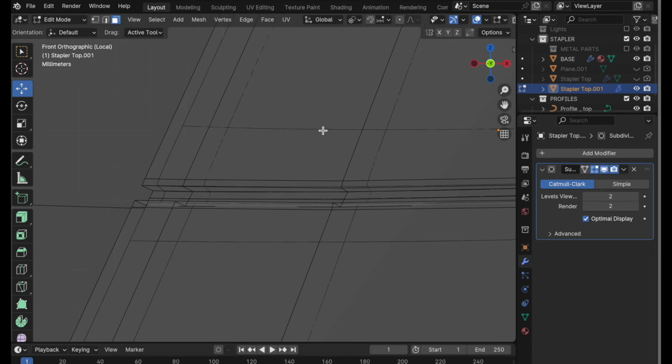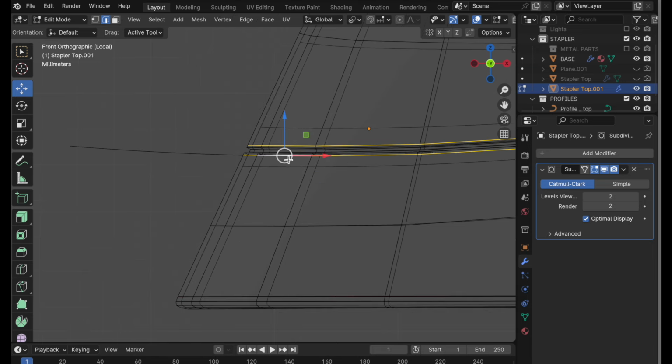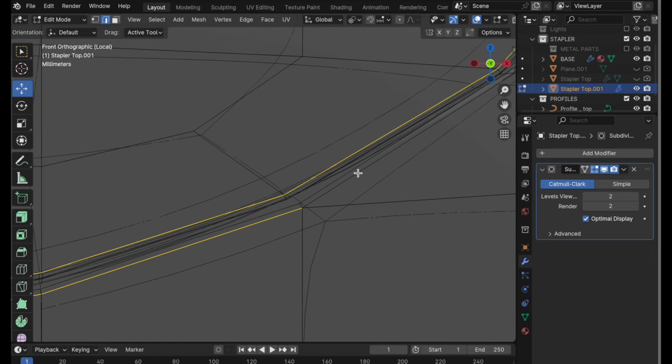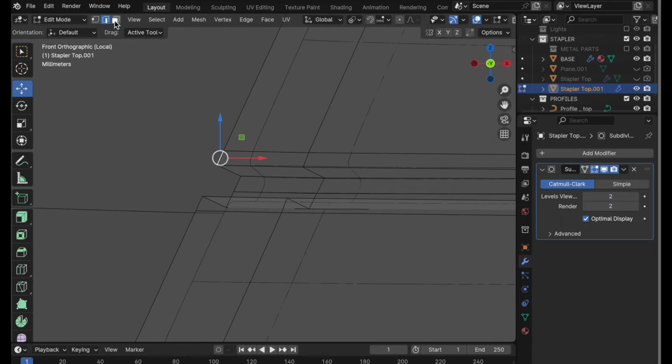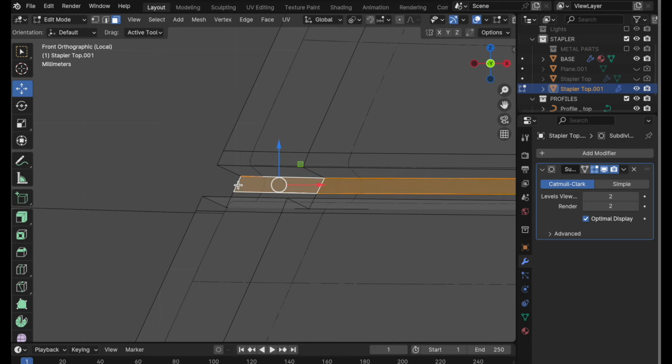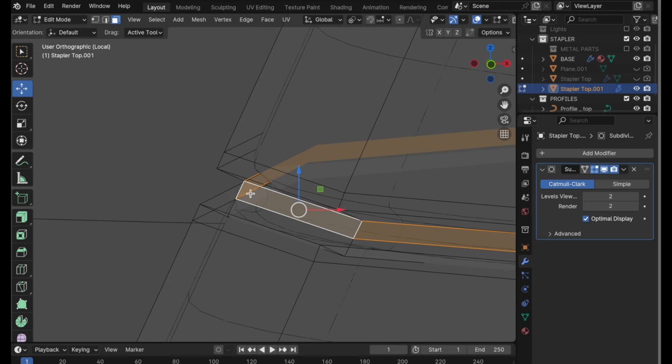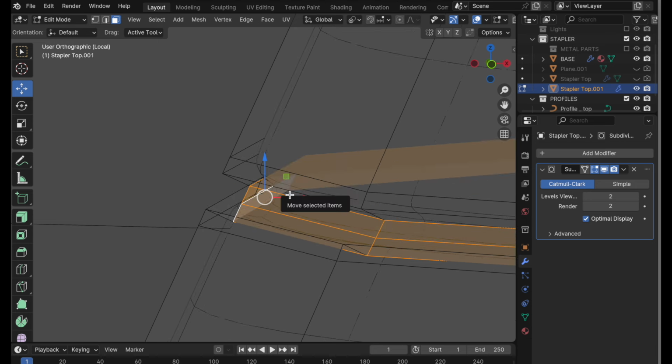We can see the subdivided boundaries. So our thin polygon here, these are being subdivided and being pulled all the way up there. And I really want to get it concentrated. So we need to do a loop select around, but we're going to have a problem. The loop select is going to cut out at this corner intersection. So an easy way to do this, to get that, is to come back in, double click here, hold the shift key, double click, and then do an expand selection.